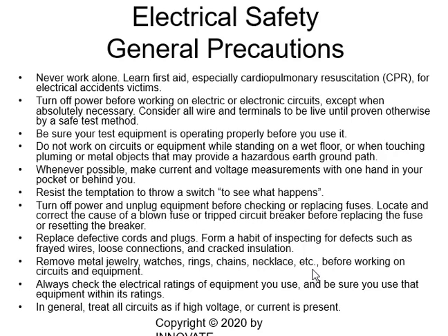Always check the electrical ratings of equipment you use and be sure you use that equipment within its ratings. In general, treat all circuits as if high voltage or high current is present. Those are a list of general precautions that you really need to remember. They are extremely important.